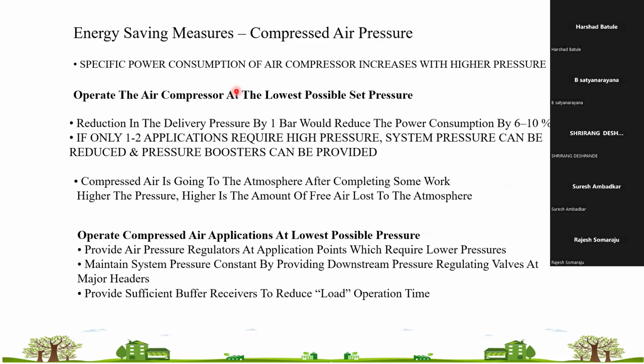For air-cooled compressors, can we connect the de-superheater for hot water generation? Yes, we can connect, but we can't reuse the energy from the hot discharge air. We can use the energy from your oil cooler and these things. So the hot air we just have to leave in the air.